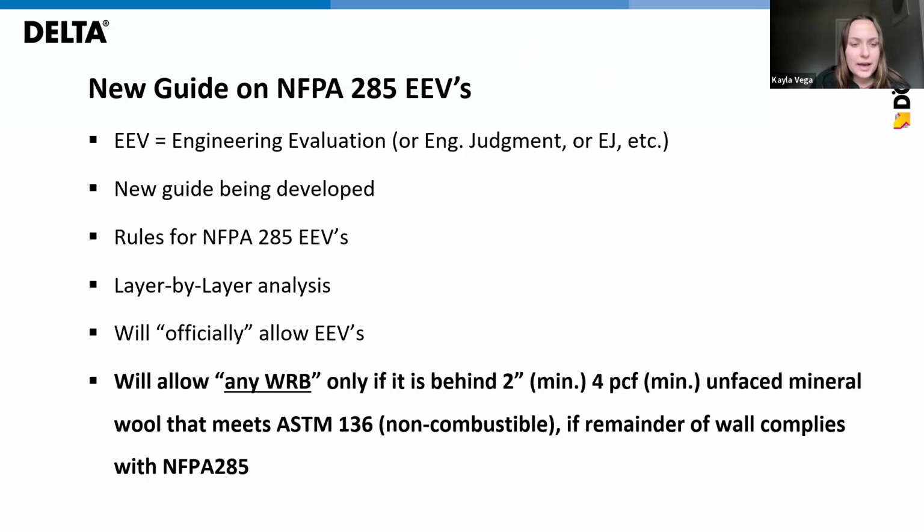Sounds good. Next we have, are most designers using exterior insulation or cavity insulation? It is entirely dependent on your climate zone and your thermal requirements. I'm in the Toronto area, so we're seeing continuous exterior insulation on just about everything. Oftentimes, you just can't get enough thermal performance with exterior insulation, so they have moved more towards steel stud and cavity insulation as well. You get into more climate friendly zones or warmer, more temperate zones, you may be able to get away with just continuous exterior.